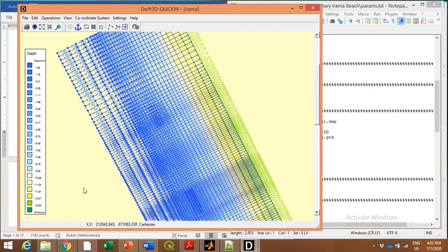If you put positive down as 1, probably it will read the positive value as the depth. Because the depth of the ocean here is -13, that is the reason why you needed to put positive down equal to -1, in order to tell XBeach that the minus is the depth, not the positive. Okay,